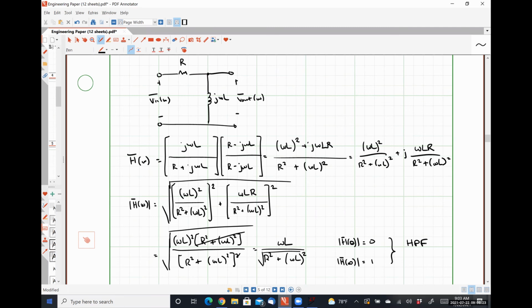Exactly. So there's almost no current flowing through the center of the wire, and almost all of the current winds up flowing around the outside surface. And the higher the frequency gets, the more and more of the current flows only on the surface of the wire. So that's another place where waveguides come into effect, because what's happening in the middle is completely unimportant, since it carries no portion of the signal.